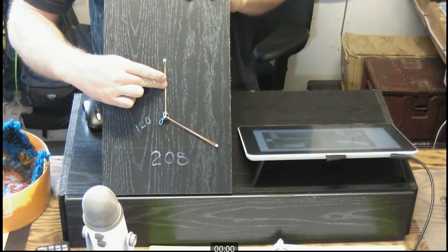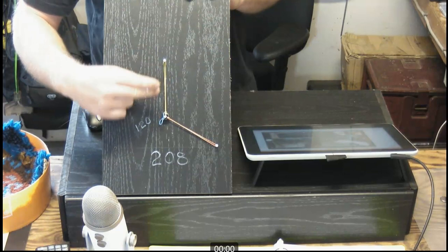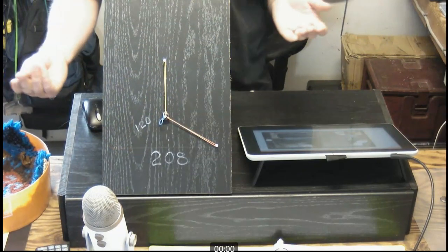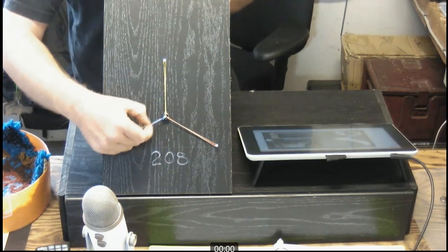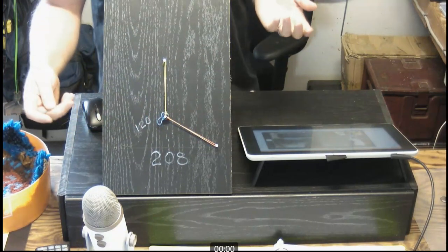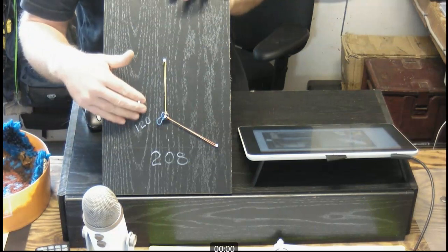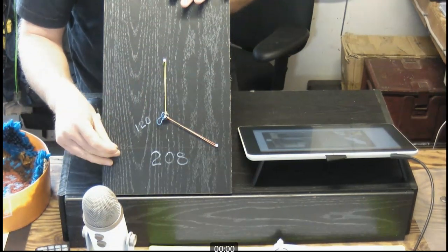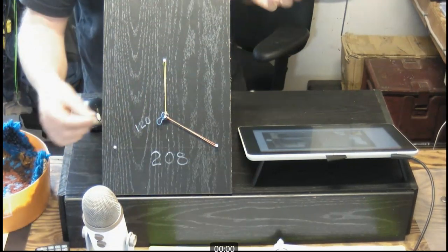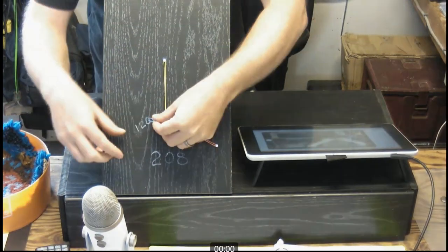So this resistance here is going to get the same full voltage that it had before. This resistance here is going to get the same full voltage that it had before. This one over here, because it's open, is going to have 0 volts across it because there's no complete path for current, so therefore we cannot drop voltage across it. That's pretty cool. It's the stabilization of the neutral.